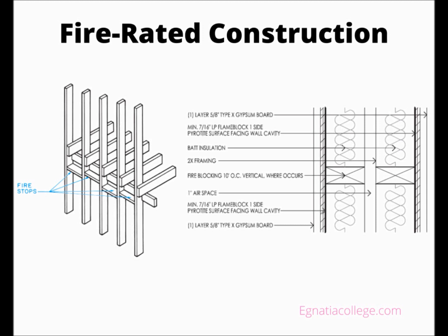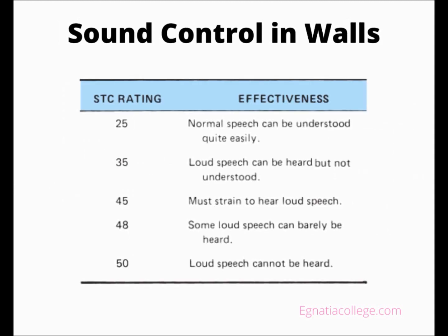Openings are usually avoided in fire-rated walls. Where it is necessary to include a door, it is made of fire-resistant material. The fire rating of the door must comply with the building code. Doors in fire walls are equipped with a self-closing mechanism.